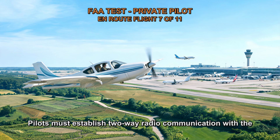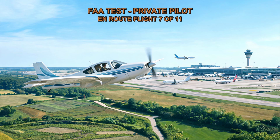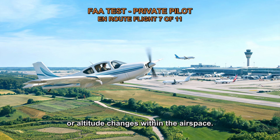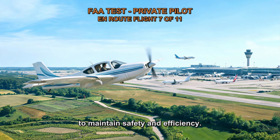Pilots must establish two-way radio communication with the appropriate ATC facility before entering Class C airspace. They are required to follow ATC instructions and obtain clearance for entry and any subsequent maneuvers or altitude changes within the airspace. This ensures proper coordination and separation of aircraft to maintain safety and efficiency.